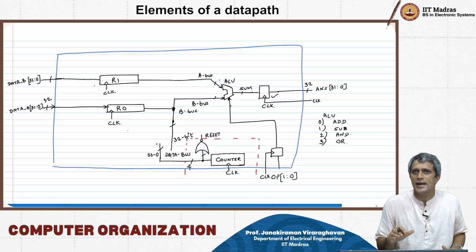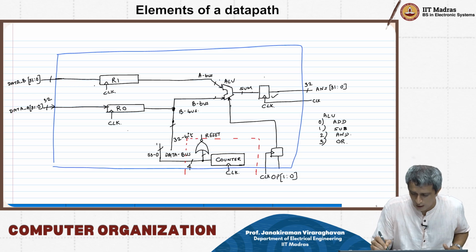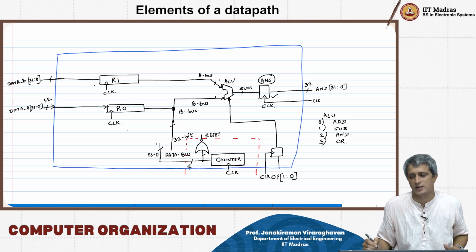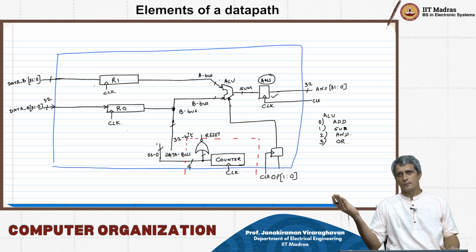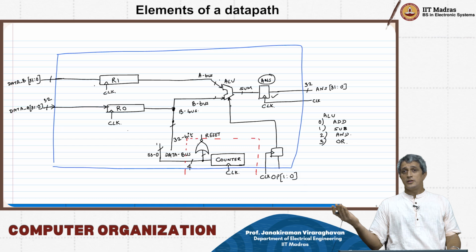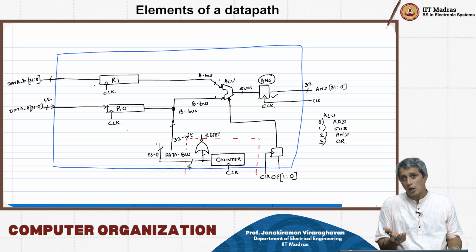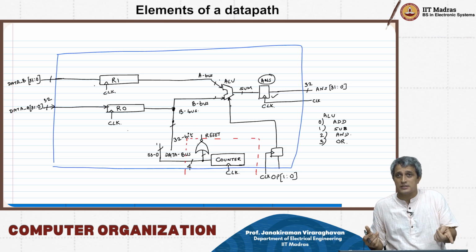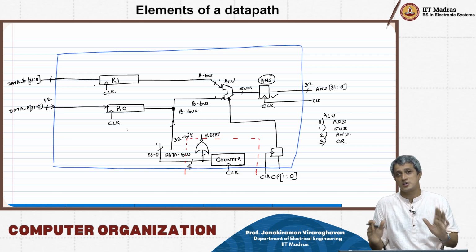Likewise, the ALU will write into the answer register, and you are going to read that out to the primary output. But there is no way for us to write into R0 or R1, or for the data bus A or B to write into the answer register directly.